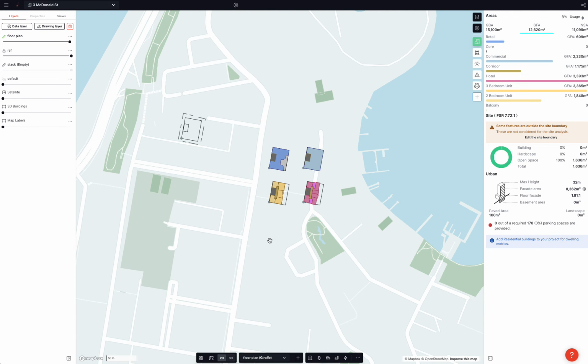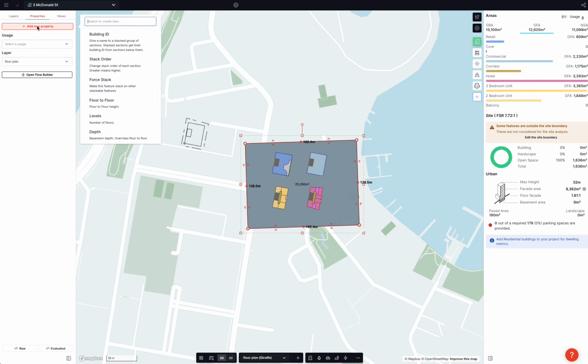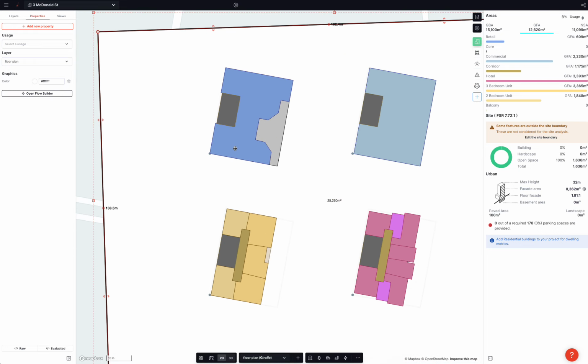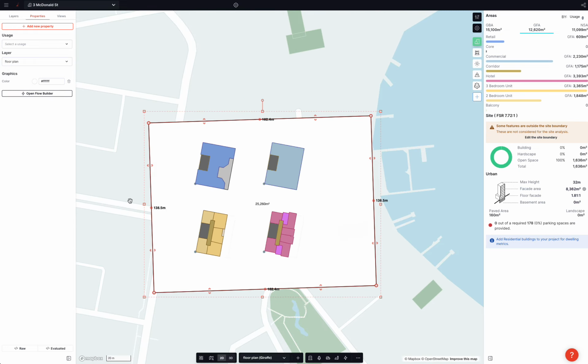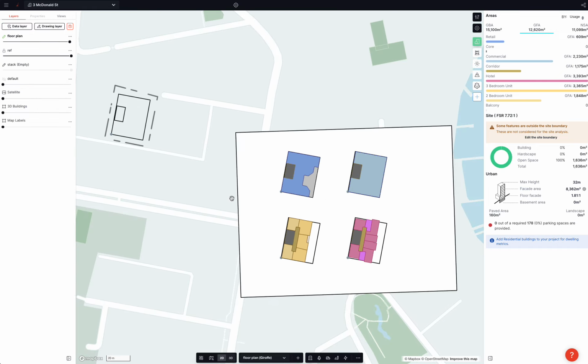And unfortunately, our infinite plane is covered with map, so we could draw something and make it wide so that sort of got rid of the infinite plane under our buildings. There we go. So now in our views, we get a true floor plan. But we don't necessarily, maybe I'll just check that on ref. Okay, so we've got a floor plan zone. This is like outside of the world. This is paper space inside the model space.